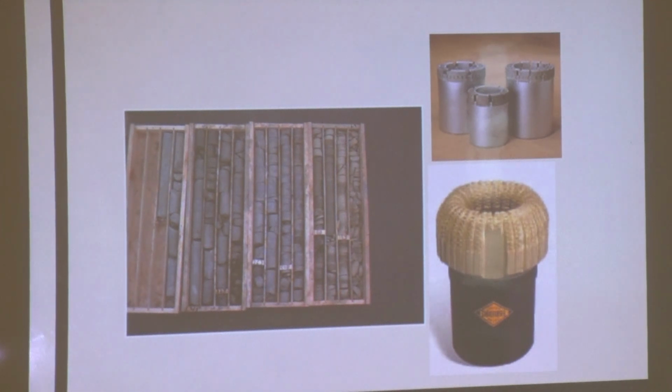So before drilling, from the surface outcrop you have to predict in which direction you will drill, so that you can capture a large amount of joint sets. This is also based on experience. A good engineer, a good geologist can guide you as to which direction you should drill to recover. So it is also very subjective, so you need to take care of this in future when you consider this kind of parameter in the field.